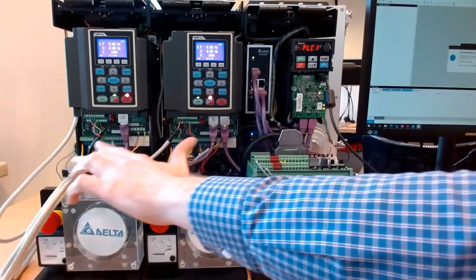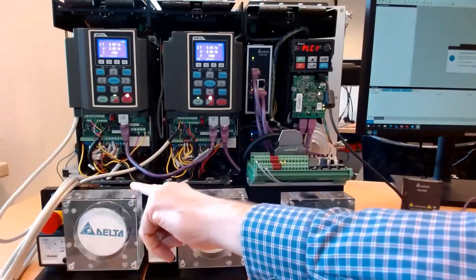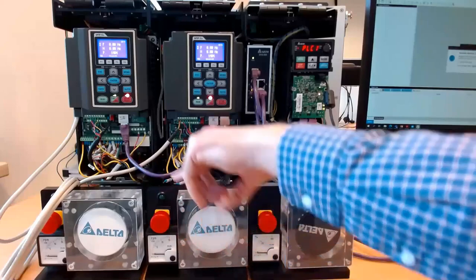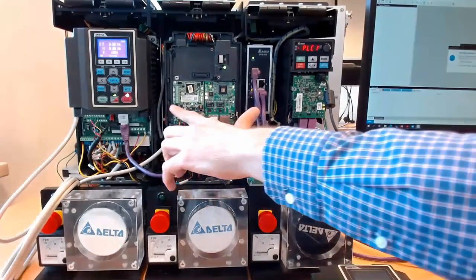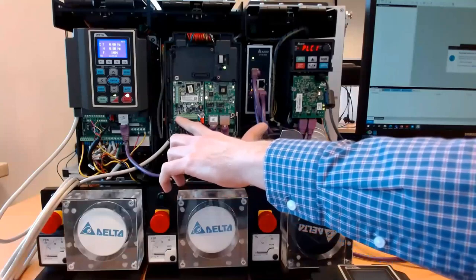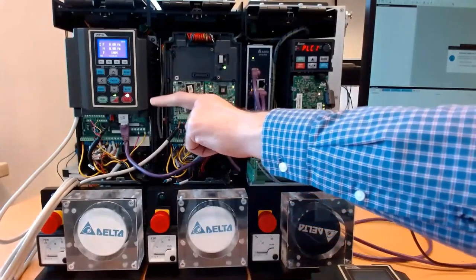I also have a PG card on each of these drives. So both drives are running in field-oriented control, PG, so that's closed loop. And both of them are running a PM motor. Now, all PG cards have different terminals. So you have firstly PG1 for connecting the motor. You have PG2 for connecting an external source of pulses. And then you have PG out, where you can get pulses out to another drive.